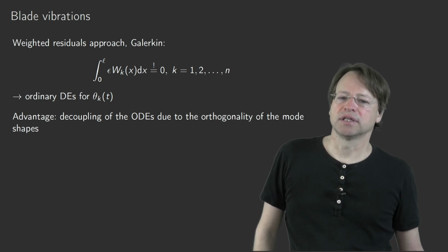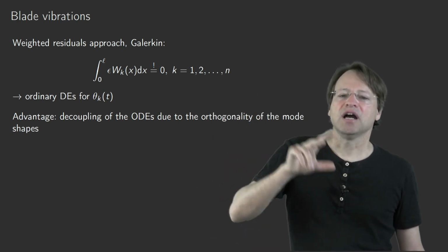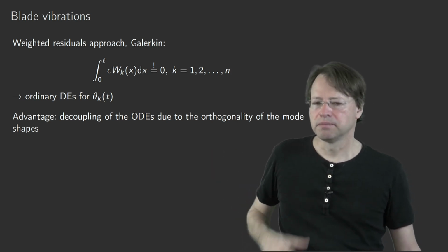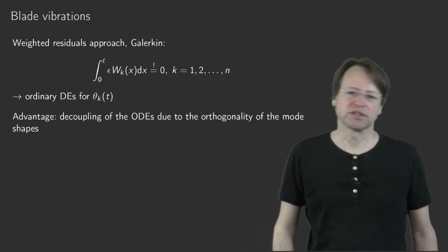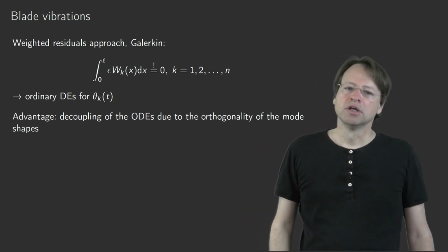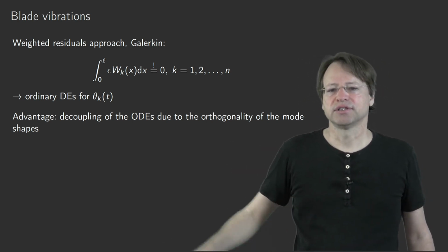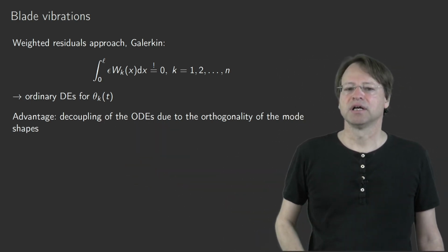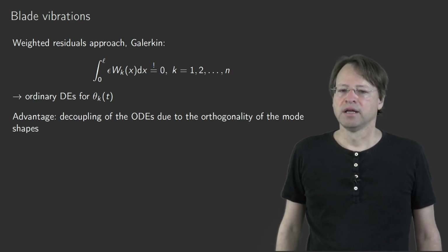because we have that orthogonality relationship, and the decoupled ordinary differential equations, well, they are second order linear ordinary differential equations. So if they are decoupled, they represent single degree of freedom oscillators. So these decoupled ordinary differential equations are easily solvable even analytically.